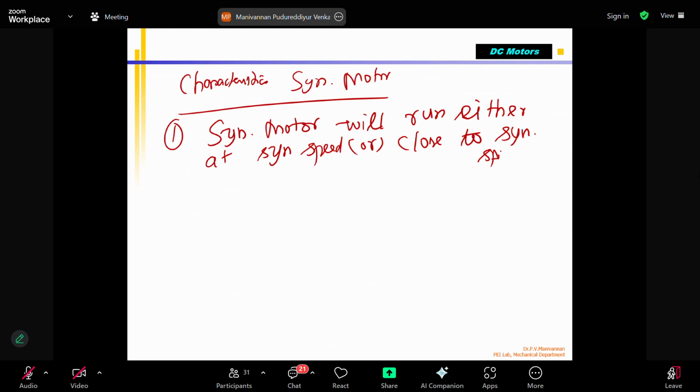Maximum speed will be rotor speed and synchronous speed. NS is called synchronous speed. NR is called motor speed. Some books call it NM, correct? These two will be equal in no load condition, with very little friction, in small motors where the inertia of the motor is less. The mass of the rotor decides, and also the less friction, good bearings, all those things.